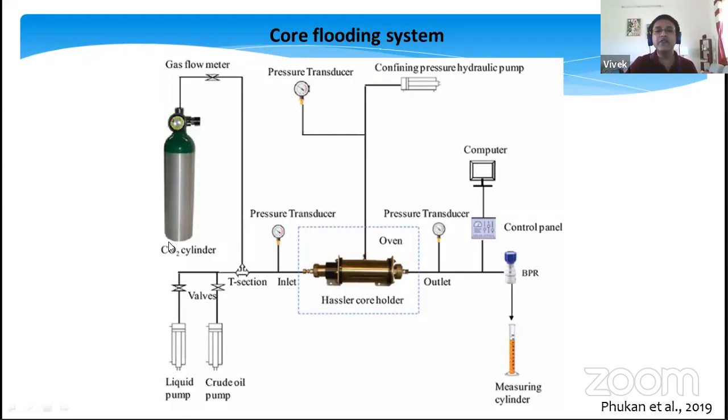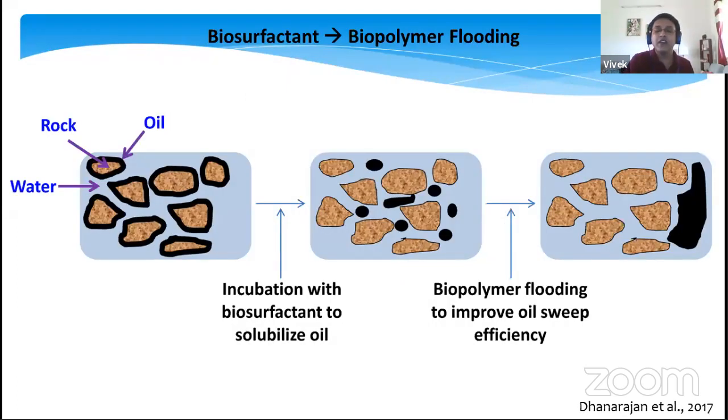So after secondary recovery, we inject our compound of interest, that means a flooding agent such as biosurfactant and biopolymer, to see what additional recovery we are able to achieve through this tertiary recovery operation. This is the ultimate aim: we are trying to simulate the condition at lab scale and achieve improved recovery. With this optimal condition, one can replicate it in the actual field, but it requires much more understanding about the actual scenario underneath the earth to implement this.